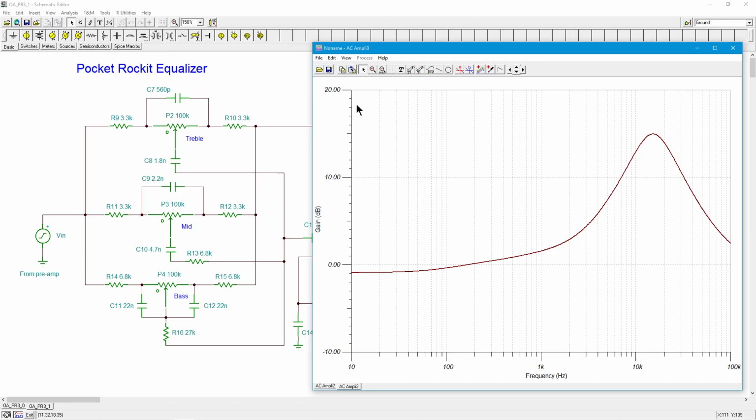Boom. Okay, so now you can see the scale has really changed a lot. So here's our 0. There's that little dB that we saw down here at 10 hertz. So this comes up, starts to peak, and it's peaking, right? This is 10 kilohertz, that's 20. So it's peaking actually right around maybe 15 kilohertz or so, okay? 16 kilohertz maybe. And then it's starting to drop off.